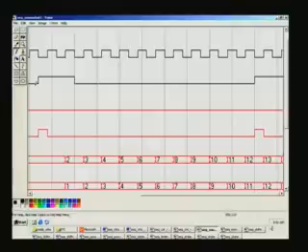You have applied the first trigger, it started working, and while it is working, if you wantonly trigger it, it will not retrigger, it simply ignores any number of such trigger inputs. Although the rising edge of run delay is still encountered, it will be ignored because the counter is already servicing the previous trigger.